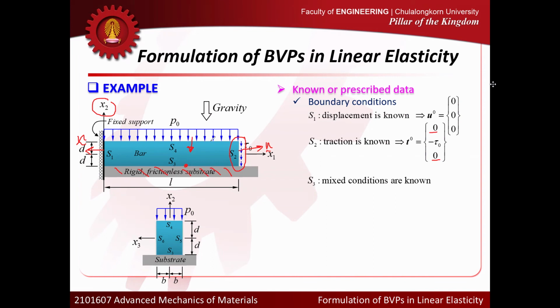So when you apply the force to the body here, to the beam here, the contact point on the contact surface can move freely in that direction, right? Because we don't have the restraint from the friction. So if we look at the movement in that direction and that direction, we don't have any restraint against the movement. What does it mean? We don't have the force generated in the two directions here as well, right?